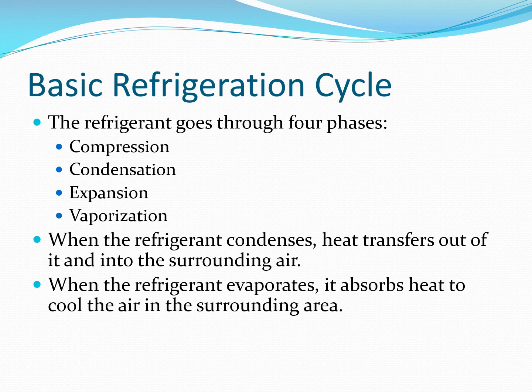So if you apply that to what you know, in the condenser, heat transfers out. So we're giving off, we're displacing the heat. Some of you may be used to a window unit air conditioner. If you ever walked by a window unit air conditioner on the outside of your house, think about what is coming out of that unit. And if any of you have done this before, you realize that it's blowing off hot air. And that's because the air conditioner condenser on that window unit is on the outside of the unit. And that's where we are giving off heat.